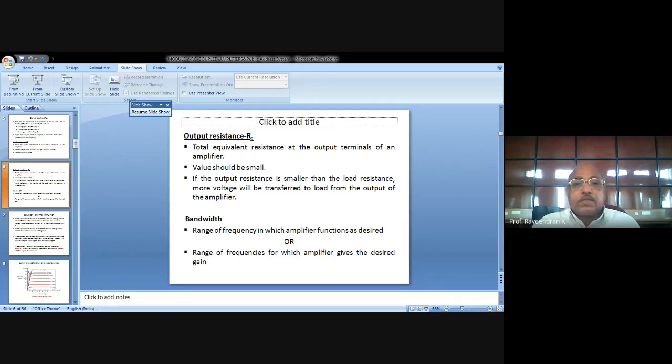Now we will see the voltage divider bias, or self bias. The voltage drop across R2 forward biases the base emitter junction. This causes the base current and hence the collector current under zero signal conditions. Actually, when we create the DC operating conditions, there is no signal applied, isn't it? There is no signal applied for biasing the transistor. Only DC voltages are applied to put the transistor in sufficient operating conditions, that is base emitter forward biasing and collector base junction reverse biasing, so that a DC condition is maintained before operating this configuration as an amplifier.